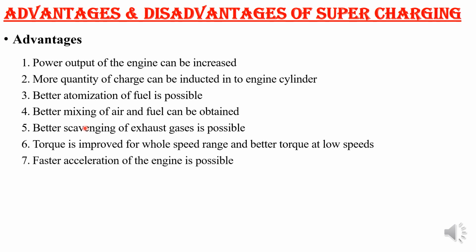Then forced acceleration will be there, or faster acceleration of the engine can be possible. Then the specific fuel consumption can be lower slightly, because you can see that it will have a better combustion, and to get that power, less fuel.